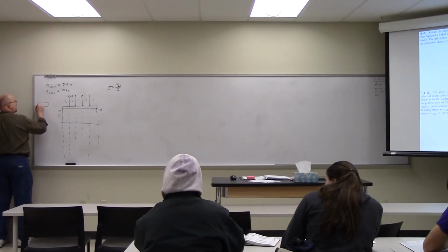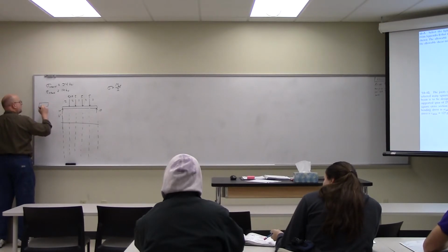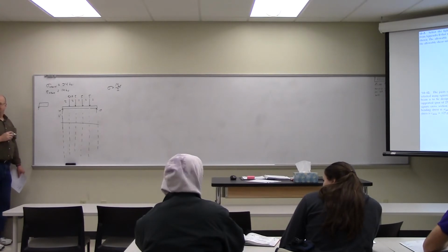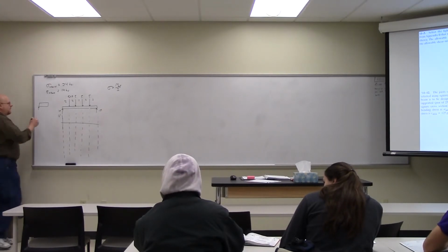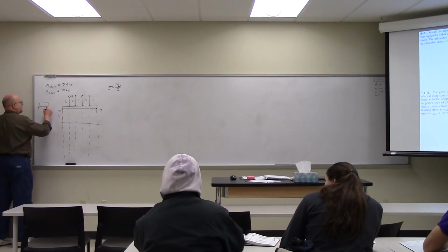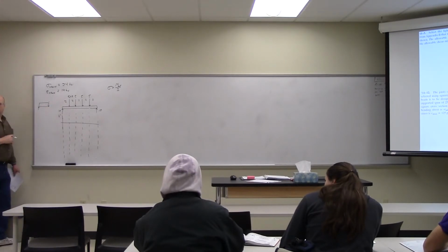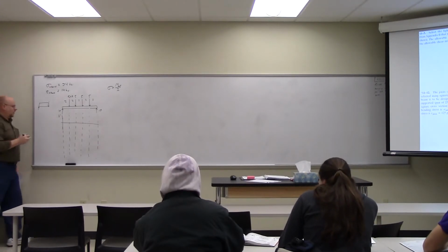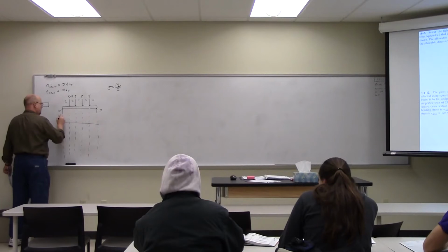Right, we have a force pushing up here. Oops, sorry. But a positive shear. So, what was that? Well, shear positive convention is downward, so it's a positive shear, but a negative force. Right, so you're saying that is positive. Right, it's a positive shear because it rotates it clockwise. There you go, okay. 10.